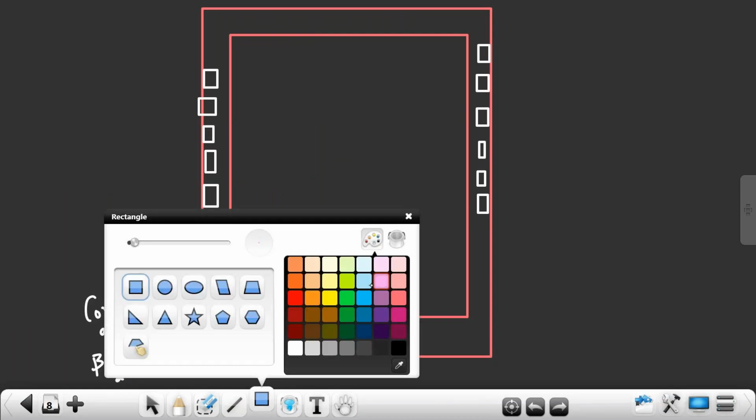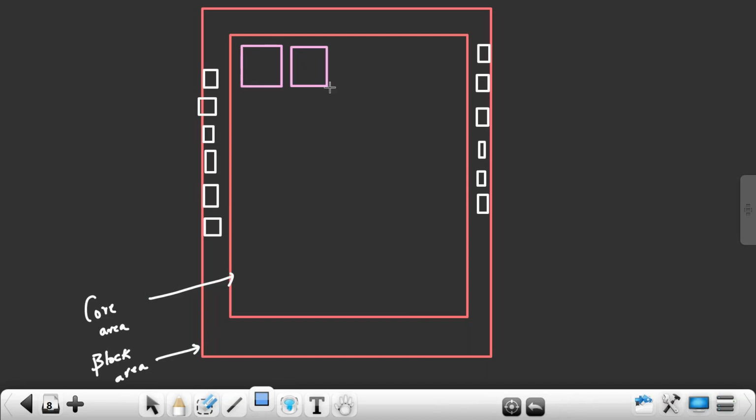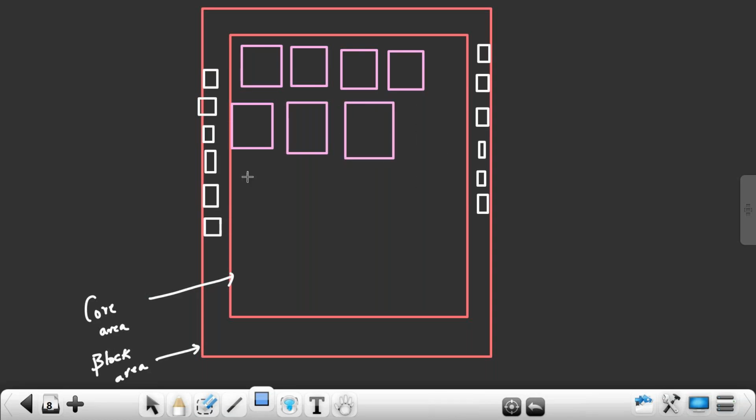So first we do macro placement because macro count will be less, right? The count of macros will be less compared to standard cell count. Standard cell count will be in the range of 30 lakhs, but macro count will be in the range of 10 to 100. That's it, not more than 100. In one design it can be 10, in some other design it can be 100, but generally not more than 100. Rare case you can have 250, 300. It's very rare case, right? But generally it will be within 100, right? So first place these complex cells like this. That is called as macro placement.